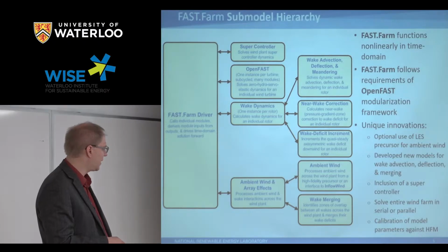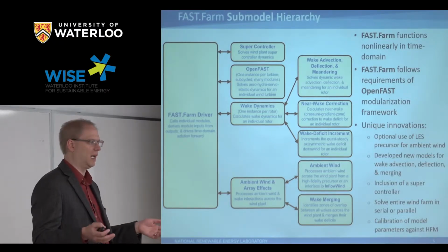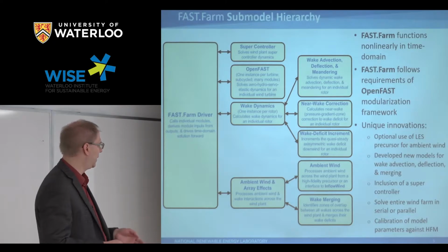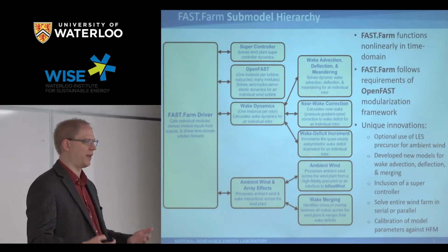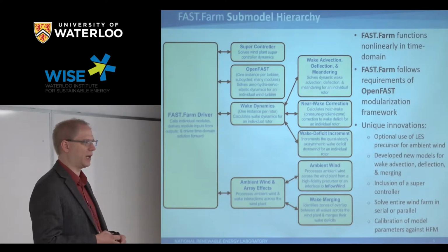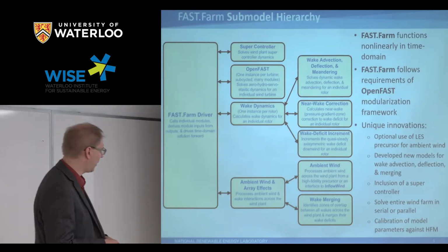And then the idea is, if you create a database of these sort of wind conditions for your farm, you can then, with FAST.Farm, take that flow and actually embed the turbines and the wake array effects and do the actual wind farm simulations quite quickly, but all based on the same sort of background flow.